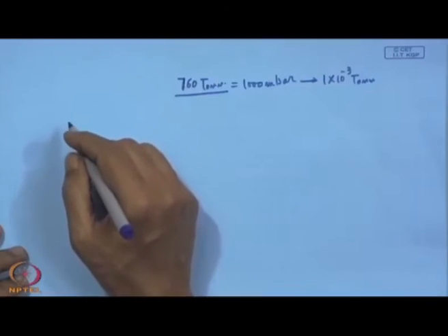Actually, it is the heat loss of a heating element. When the heating element is hot, because of some conductivity of the medium, some heat will be taken away. In this case a heating element is put inside the gauge, centrally placed, and when it is hot, the gas molecules can take away the heat just by conduction, and when they hit the wall of the gauge, this heat is transferred to the wall.